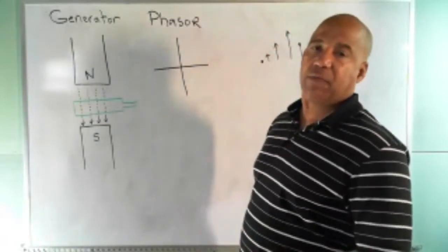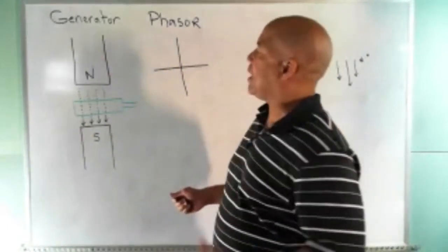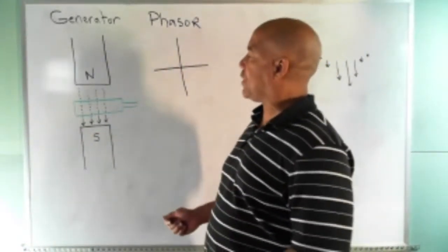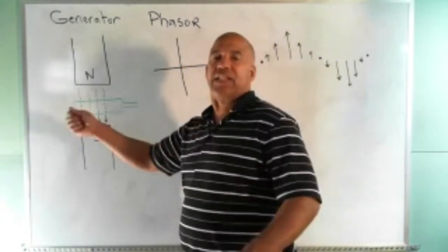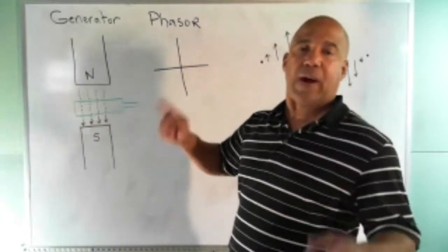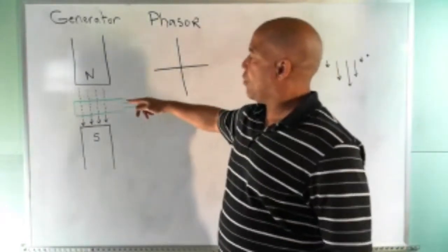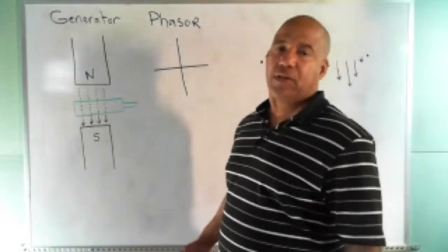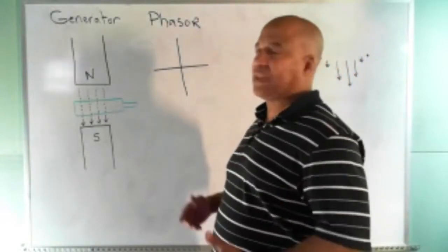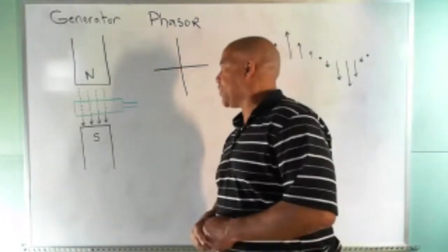Based on Faraday's law, to induce a voltage I need a magnetic field, a conductor, and motion. With linear motion back and forth, I can induce a voltage across a wire, but that's not very practical. Setting it up so the coil rotates in the magnetic field is much more practical, and it's easier to design a generator based on that kind of motion. And so we have the rotating machines.